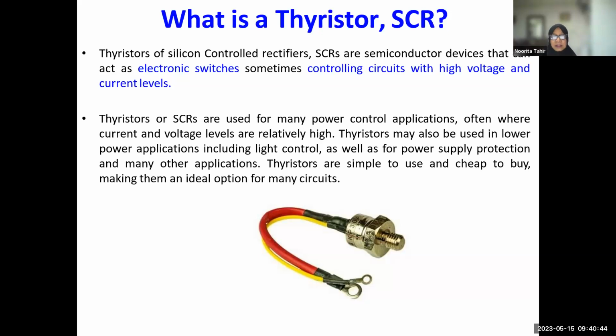Thyristors, on the other hand, are semiconductor devices that tend to stay on once they are on and tend to stay off once turned off. A momentary event is able to flip these devices into either their on or off state, where they will remain on their own, even after the cause of the state change has been taken away.